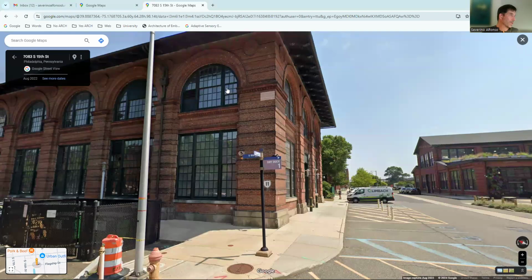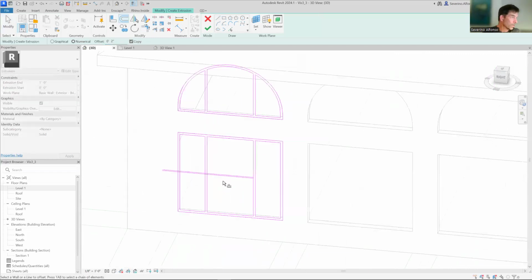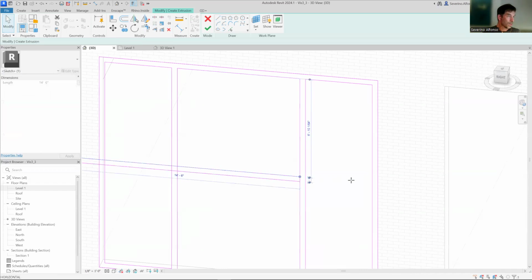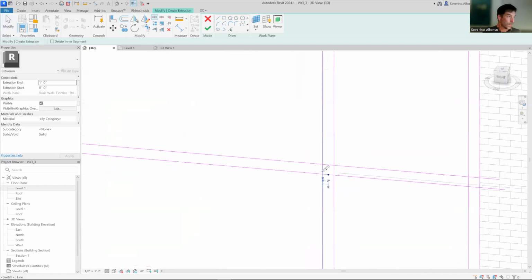There's a number of other lines, maybe that horizontal one, and this one could be good to have. So I'm going to do a line here, an offset. I'm just going to do 2 in one direction and 2 in the other one, and delete the center one. I could extend this. I can just select the edges to do that and do SL. In this case, we need to trim all of those.